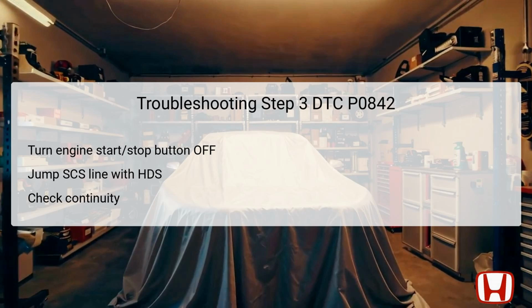Now you will need to examine the continuity between two test points. One at the transmission fluid pressure switch A, second clutch, connector, and the other at the PCM connector B, 51P. By determining if there is continuity, it becomes clear whether a short to body ground exists in the wiring. Should there be continuity, it indicates a short in the OP2SW wire, which requires repair. If no continuity is found, it suggests the wiring is intact and the PCM may need replacing.